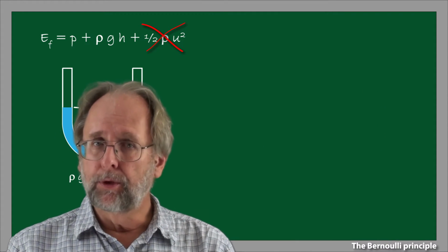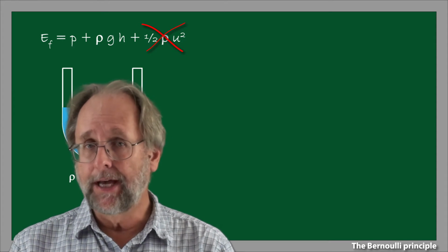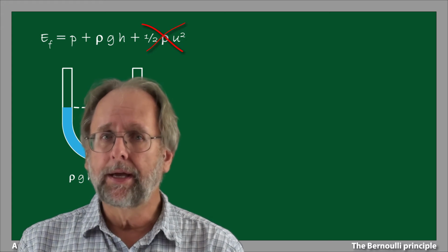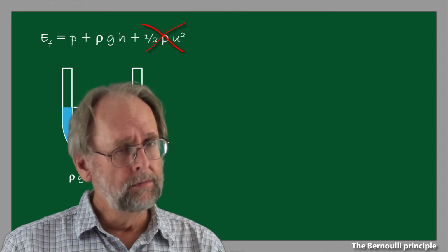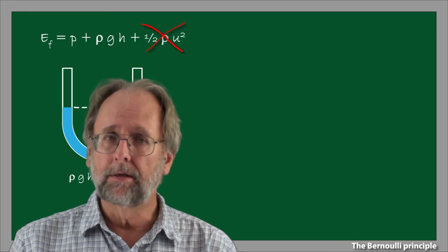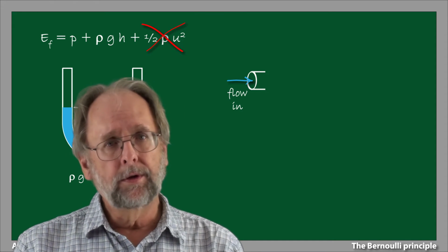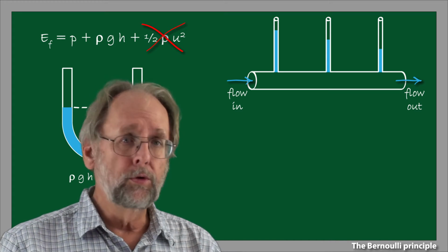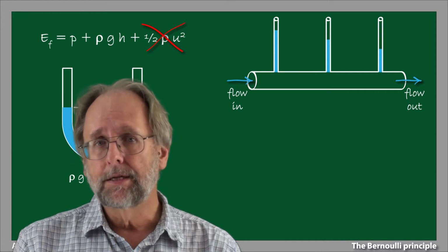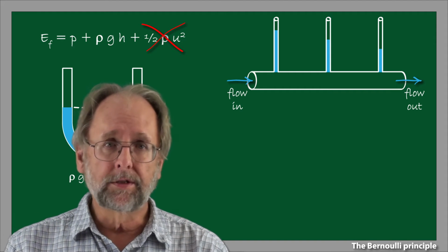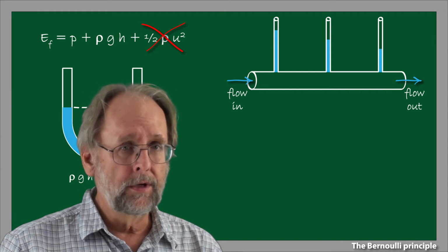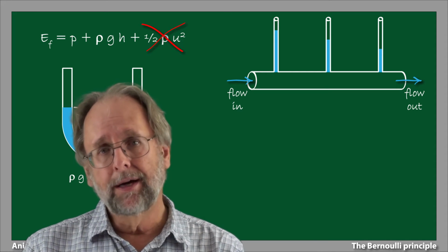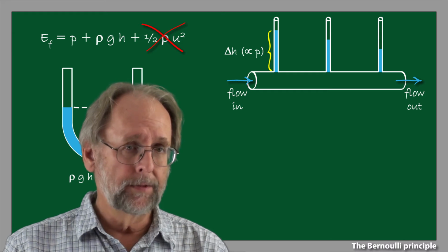Okay, we've seen what Bernoulli's law tells us about energy in static fluids. What about moving fluids? Here things get a little more complicated and in some ways paradoxical, but Bernoulli's law explains it all. Let's start with a horizontal tube through which fluid flows. Let's make the tube uniform in diameter for now, and let's set in place vertical tubes along its length so that we can measure pressure along it. We're measuring pressure manometrically, of course, that is, by measuring the height to which the fluid is elevated.